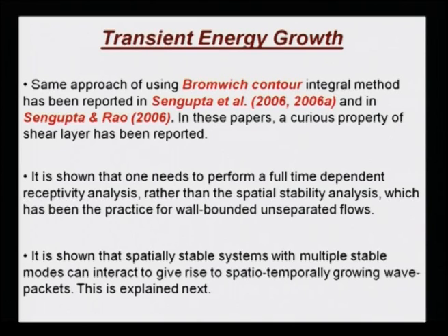the shear layer instability: when we perform a fully time-dependent receptivity analysis instead of performing spatial analysis for wall-bounded unseparated flows, we found that even though the flow, if studied from a spatial stability point of view, is stable, with multiple modes present that are all stable, when they interact, they can lead to a kind of spatiotemporal growth. This was something that was not known for more than the last 20 years.